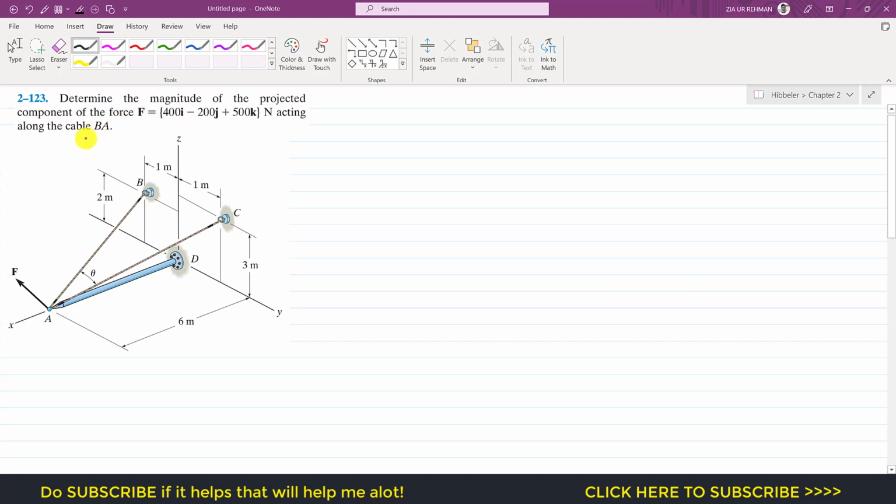Let's solve this problem from engineering statics. Again, the problem says to determine the magnitude of the projected component of force F acting along the cable BA. So we are given this force F as a Cartesian vector, and we are required to determine the magnitude of the projection of this given force along this BA cable. We can find that projection by applying the dot product.